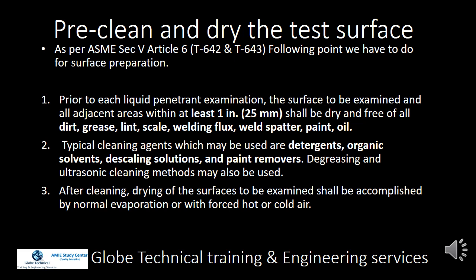Prior to each liquid penetrant examination, the surface to be examined and all adjacent areas within at least 1 inch, 25 mm, shall be dry and free of all dirt, grease, lint, scale, welding flux, weld spatter, paint, oil. Typical cleaning agents which may be used are detergents, organic solvents, descaling solutions, and paint removers. Degreasing and ultrasonic cleaning methods may also be used.